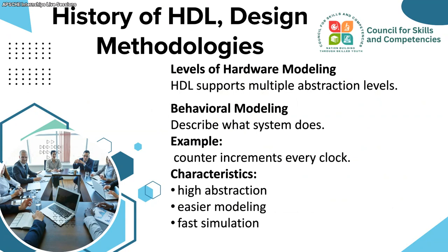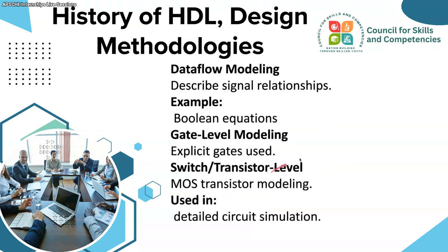Like a teacher's behavior is to teach something. For example, a counter increments every clock. That is its behavior. With this modeling, you get a high abstraction, easier modeling, and fast simulation. We will see these one by one in future classes, but try to get the terminologies. That is behavioral modeling.